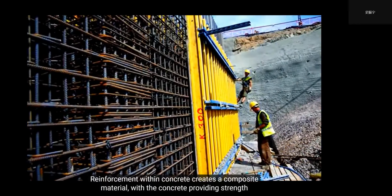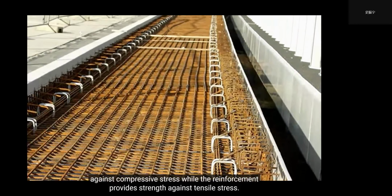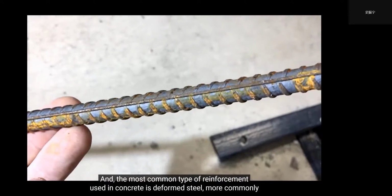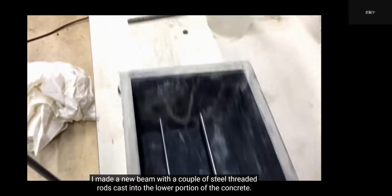Reinforcement within concrete creates a composite material, with the concrete providing strength against compressive stress, while the reinforcement provides strength against tensile stress. And the most common type of reinforcement used in concrete is deformed steel, more commonly known as rebar. I made a new beam with a couple of steel-threaded rods cast into the lower portion of the concrete.